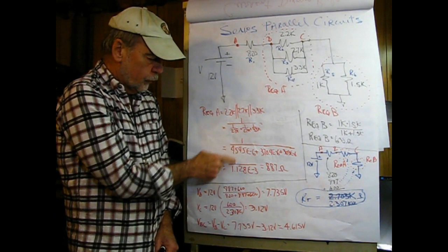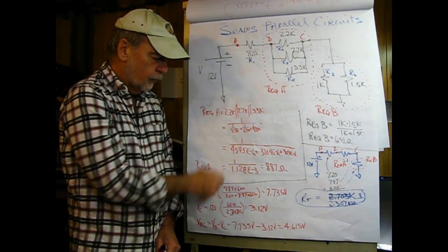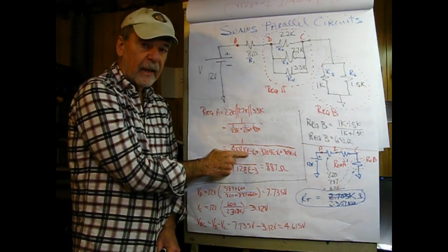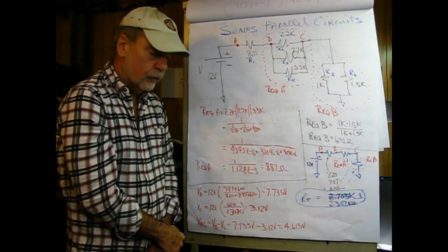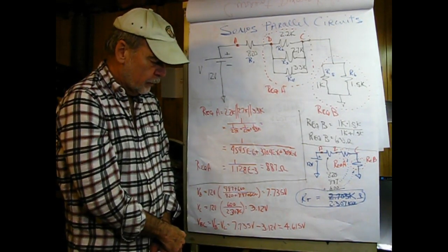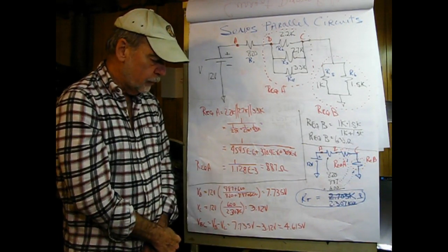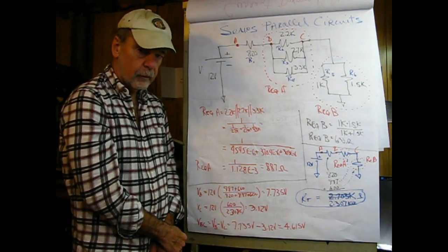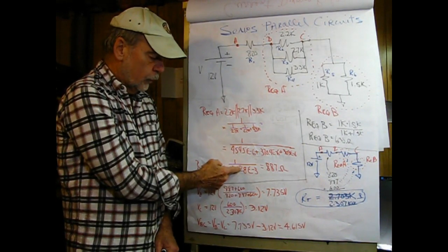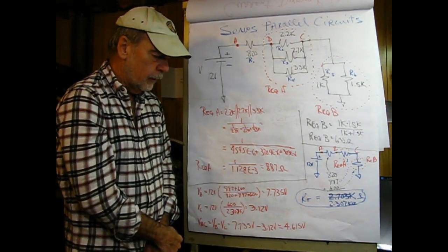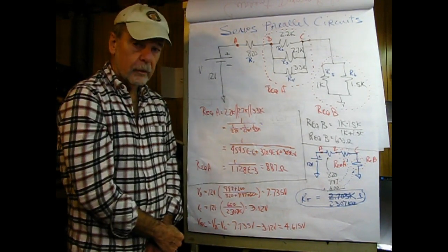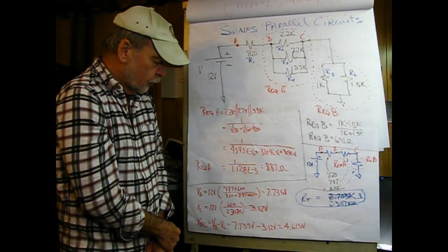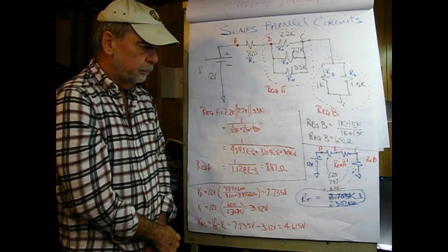That would be equal to 1 divided by 454.5 microsiemens plus, and then the same with the rest of these. Adding up the denominator gives us 1 divided by 1.28 millisiemens, and then finally doing the reciprocal gives us 887 ohms. Looking at this network, that appears to me to be a reasonable value. So that would be R equivalent A.